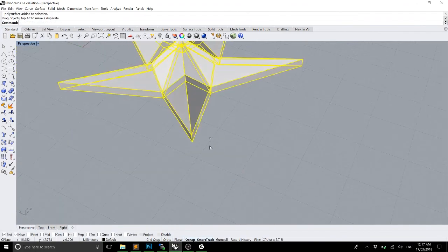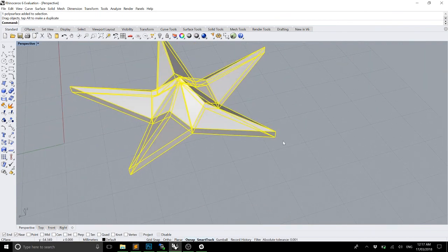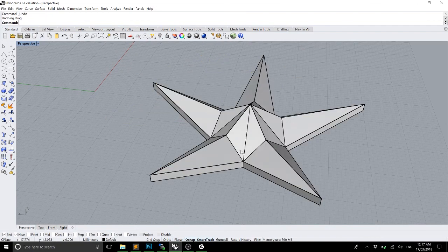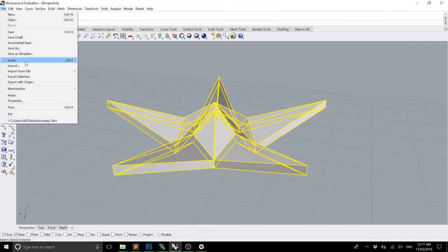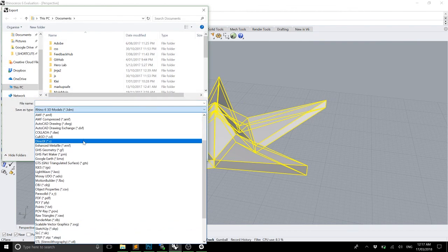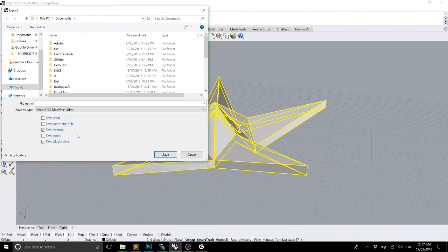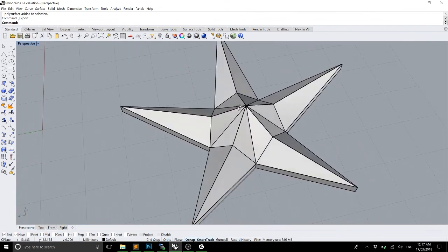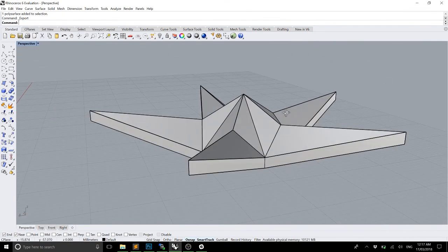You can see that as we move it, the point that was defining the geometry in Grasshopper isn't moving, so it's completely detached from the dynamic system now, and this is now selectable to be exported to STL format, which is what the 3D printers at UNSW will take. Actually, I think it's probably what any 3D printer will take by default, unless they're really special.